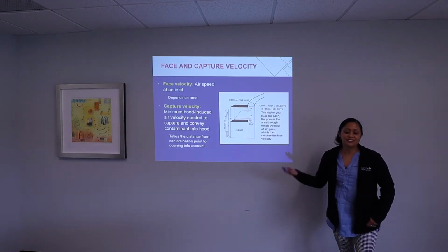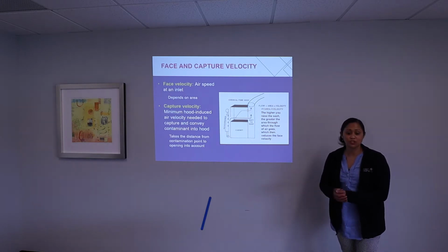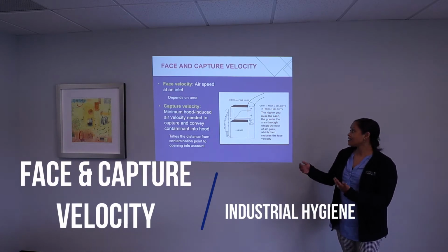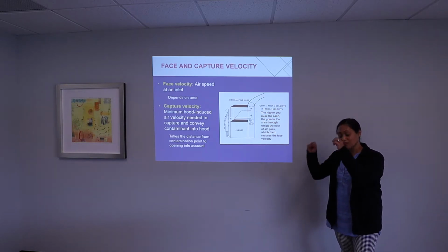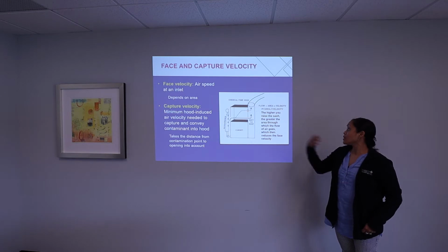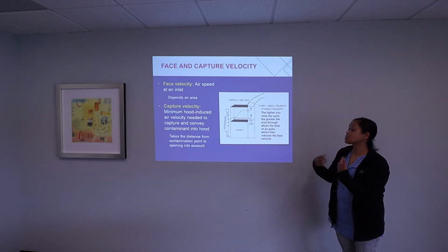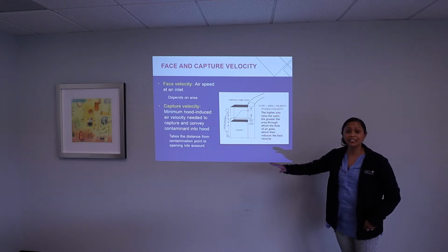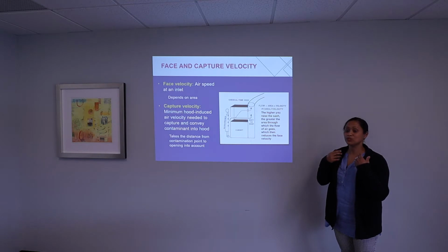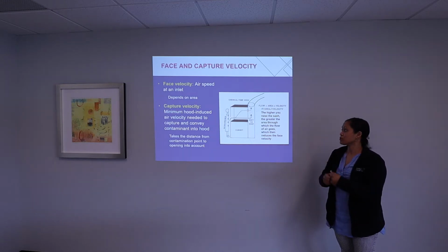So over here I have a slide that we generally put in our safety training, and this relates to fume hood use. The whole point of this slide is we are asking everyone to keep the sash as far down as possible. The reason for this is if you increase the area, you decrease what is called the face velocity, and that's the airspeed at a certain inlet. Really, you want to protect the worker by allowing the air to flow through and away. You want to reduce exposure.